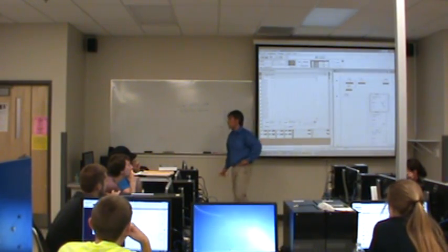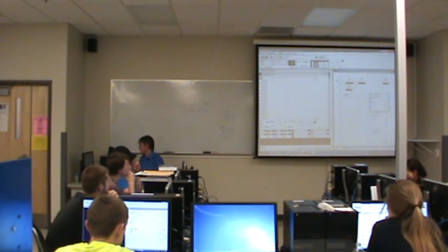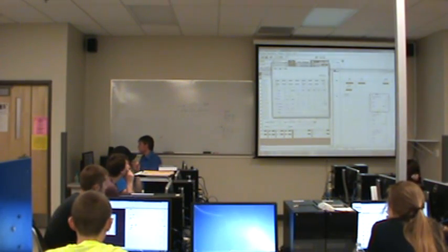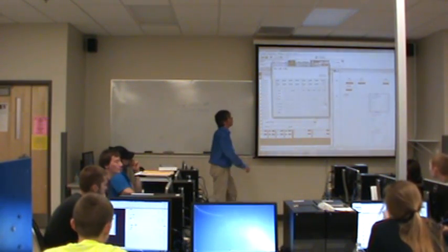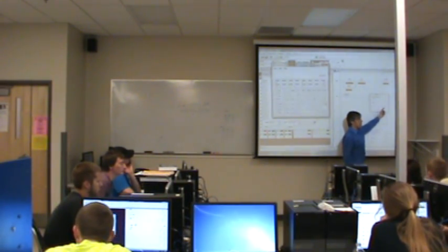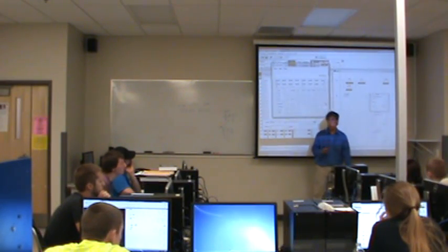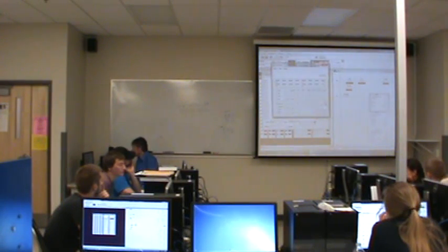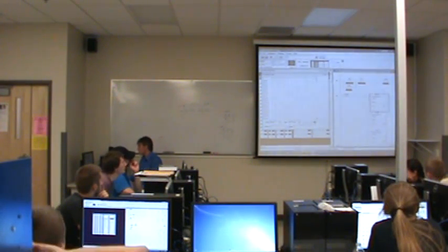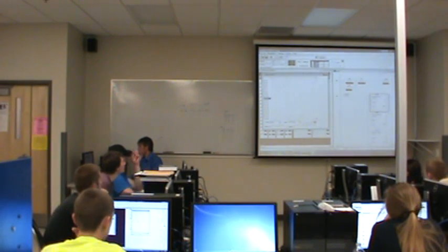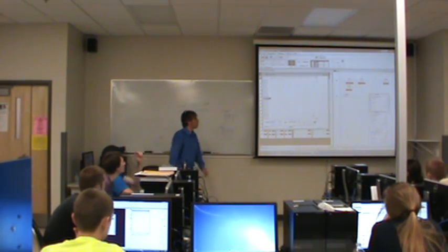In fact, let's find out what mask I used. If we take 15 in decimal and go to binary, what I used was a mask of 1111. In other words, the only bits that I want to affect in this word are the lower 4 bits, the least significant nibble. And if you look in memory, sure enough, in B3:11, the only bits I ever affected were the lower 4. You see that? All the way from 11 through 18, all I've done is use the lower 4 bits.